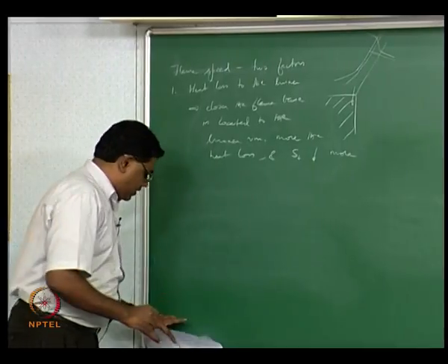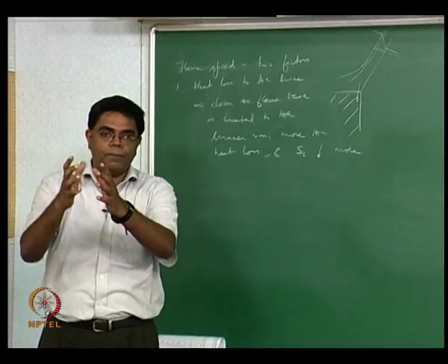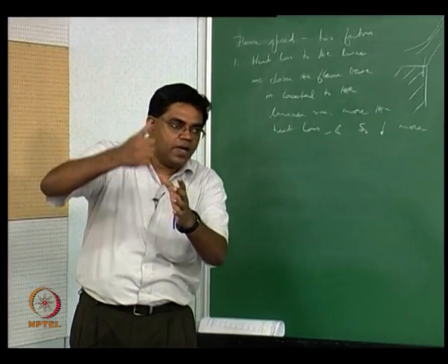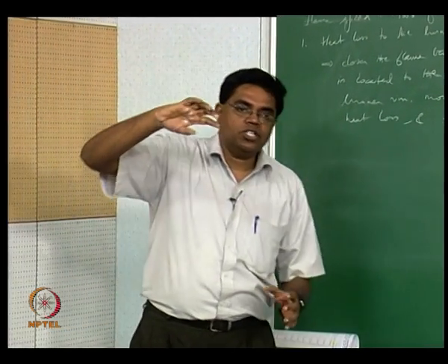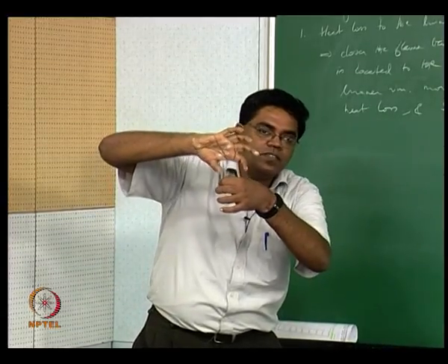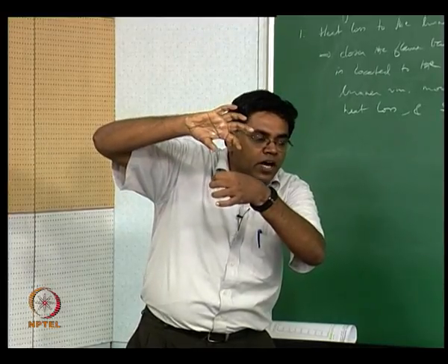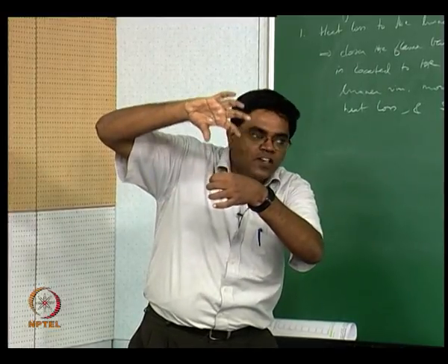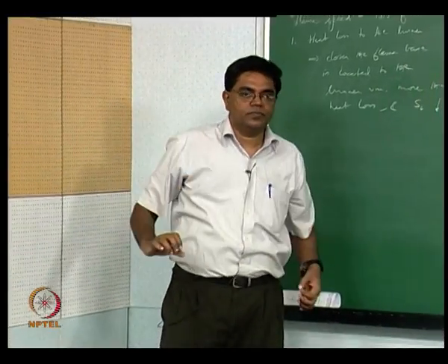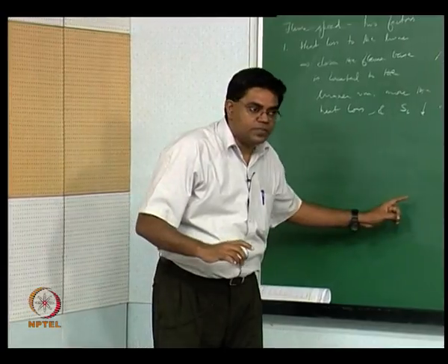What we are basically thinking is, as you have a burner and you are trying to increase the flame speed, we begin to imagine that the base is not exactly touching the rim anymore. The base of the flame is now going to go up a little bit and try to adjust its position. Why it would adjust is something we are going to see pretty soon.